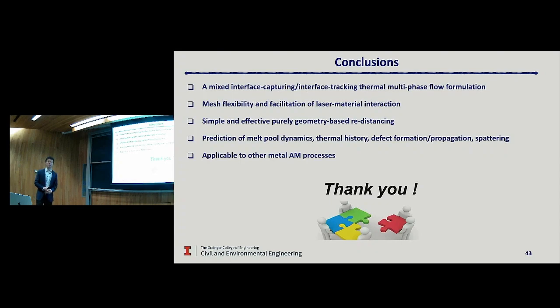Does that make sense? Yeah, this is a good point. If the laser travels very fast, you have less time to melt the material there, so you may end up with shallower depths. I totally agree with you. Our simulation is for a given scanning speed and scanning direction; for different ones, you need to rerun the simulation.